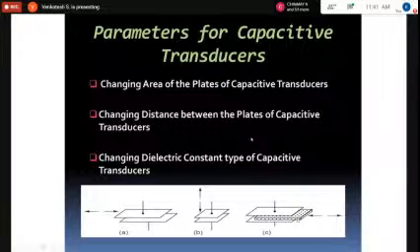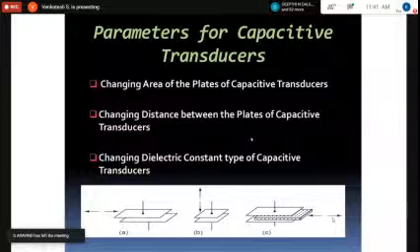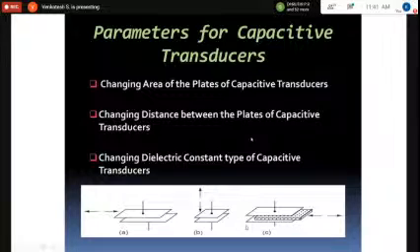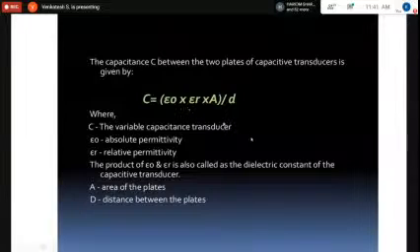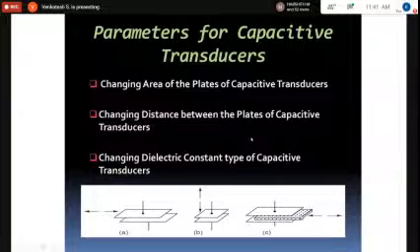So as the dielectric material is moved and epsilon r is decreasing from 50, if it were in line with the two plates, then epsilon r would be constant throughout, equal to 50 in this expression. Now it is an air capacitor plus a dielectric capacitor. It can be made of glass, mica, a ceramic material, or any other dielectric material which is a non-conductor, so that it doesn't short the two parallel plates of a capacitive element.